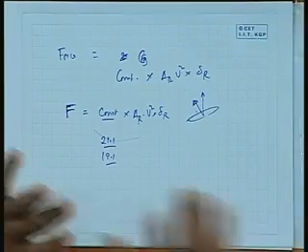To sum it all up, the rudder produces force because of its aerofoil action. So, the force is lift and drag. Traditionally, lift and drag for aerofoil sections are always expressed in terms of CL and CD, which you know for known sections. We do not have to calculate ourselves, although it can be done today using sophisticated fluid mechanics calculation procedures, but you do not do it. So, once you now know CL and CD, you can find the lift and drag on a rudder section.